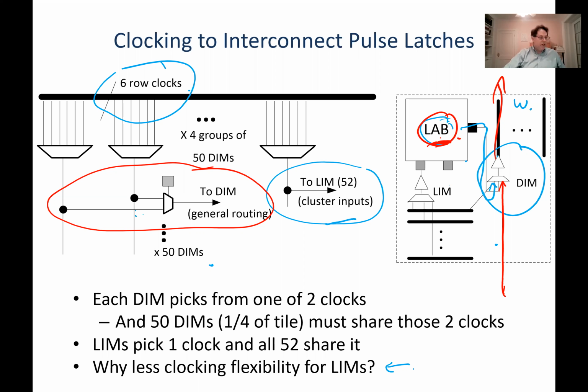If your logic block says I can only have one clock per logic block, then you would just separate out those registers. So if I'm crossing between clock domains, you put some of the registers in one logic block and then put the registers clocked by the other domain in the logic block right next to it. And that's pretty good too. So it normally comes down to you do CAD experiments and you see which one gets you better area. And one clock or two clocks both turn out to be reasonable answers, and somewhat dependent on how big your logic block is and how you choose to create your clock enables and some other things. Does that make sense? So it's not a hard limit of you must have two clocks per logic block. Most Intel chips have done that, but some, I believe, have actually gone down to one. And certainly we experimented with one, and it also works pretty well.